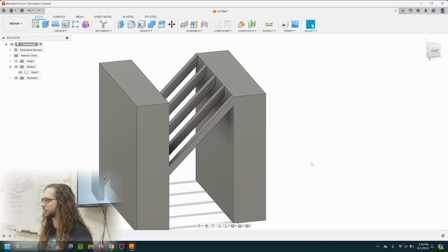Well, why did you choose to make one body before you just did the transformation you did? So you could do it the other way, right? If I had this as 3 bodies, I could select that middle body of the span, that I would select the new body when I created it using the extrude transformation, then apply the pattern on that body instead of that feature, repeat it the same way, and then use the combine tool at the end. That would get you to the same result. And if that's the way that you prefer to work, that's fine.